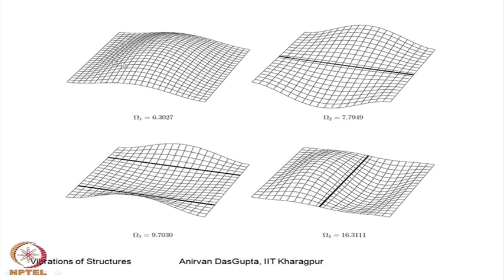You can see that the displacement here is maximum, here it is not so high. Had there been no stiffener, this would have vibrated like a beam, so the displacement here also would have been as high. Because of the stiffening effect of the beam, we have lower displacement at these edges.